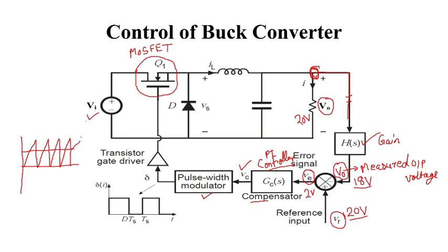This is our reference signal VC, which we get at the output of the controller, and this VC is now compared with these high frequency carrier waves. These two generate the pulses as per the logic.